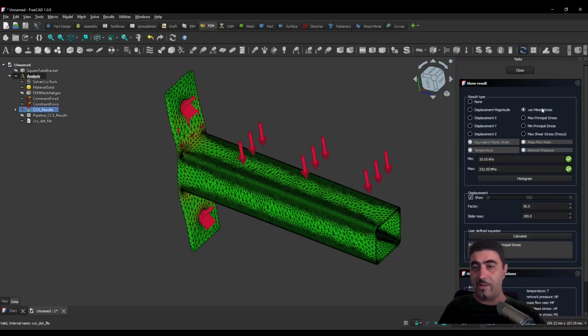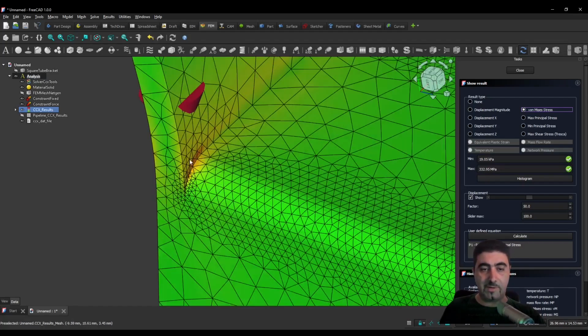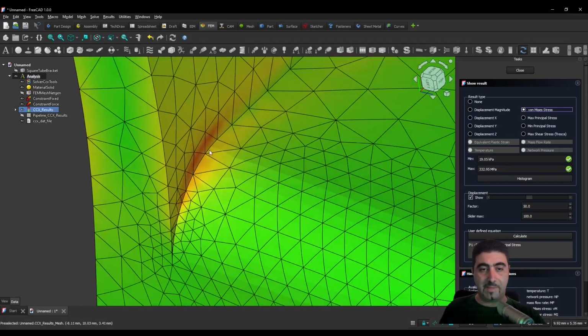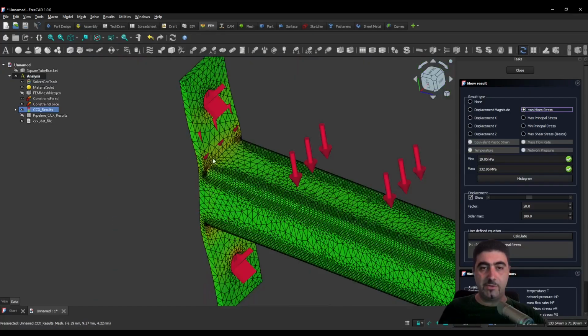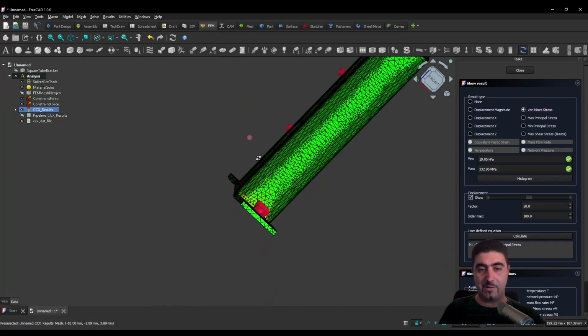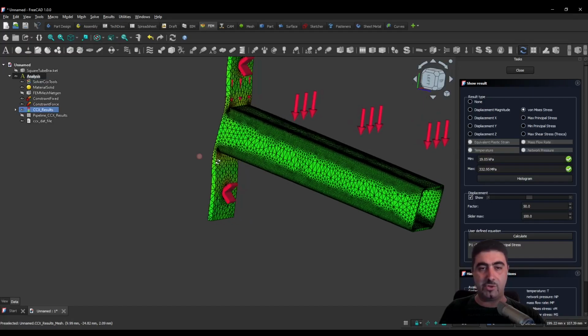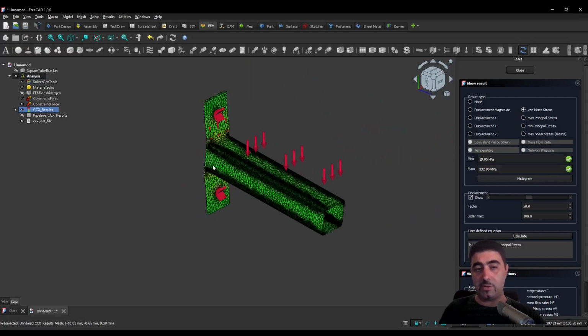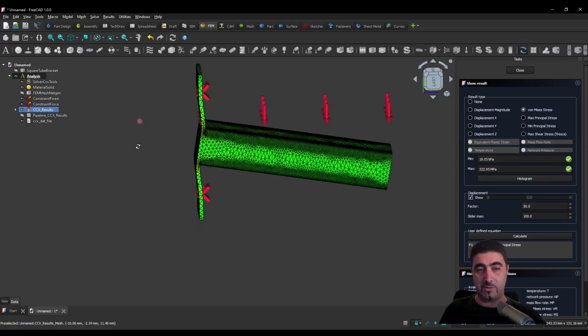So this is finite element analysis. We've got a range, right? Green is good, red is bad. Where's that high load, right? Well, if we zoom in over here, you'll see that near this very sharp 90-degree edge, we've got all of our transition from green to yellow to red. So this is where these 330 megapascal loads appear, only here in these sharp edges, which a sharp edge is a stress concentration point, right?